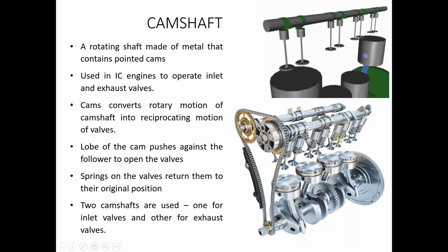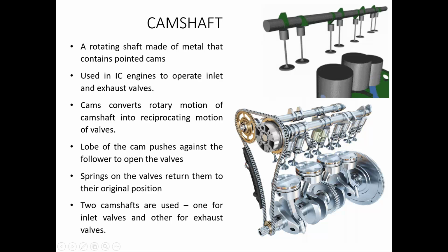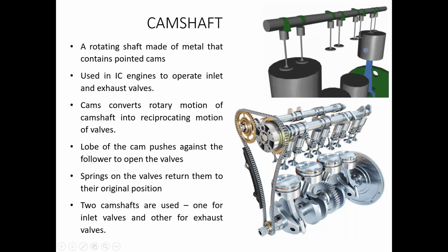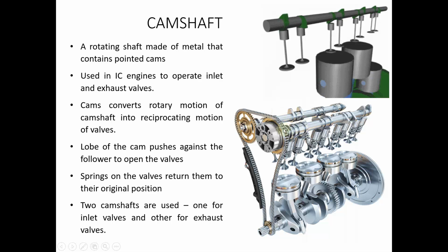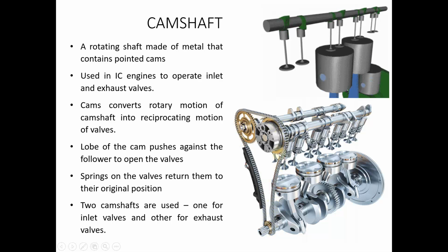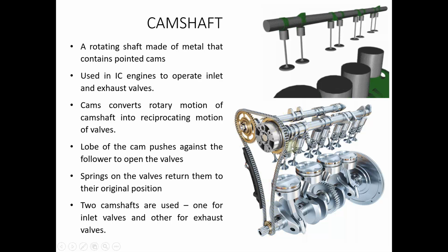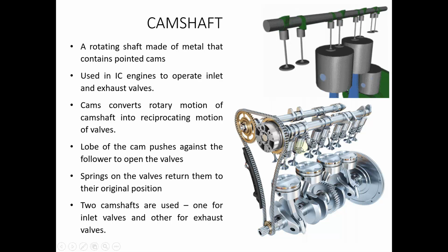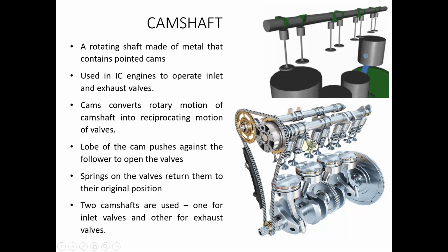Especially in multi-cylinder engines, opening and closing of the valves are very important. So in order to time it perfectly, proper adjustments have to be made on the camshafts and proper timing has to be arranged such that the cams come into contact with the valves at that point of time and it opens and closes at the appropriate time.